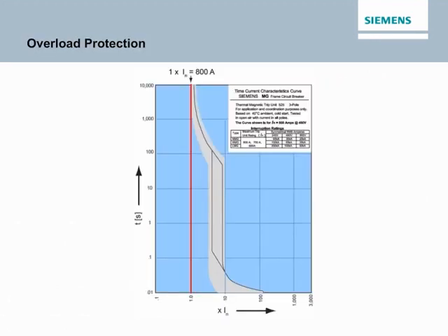From the information box in the upper right-hand corner, note that the time current curve shown here defines the operation of a Siemens MG frame circuit breaker. For this example, operation with an 800 amp trip unit is shown, but depending upon the specific breaker chosen, the circuit breaker may be purchased with a 600, 700, or 800 amp continuous current rating.